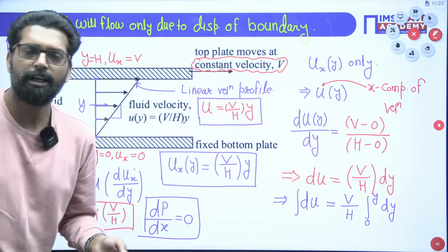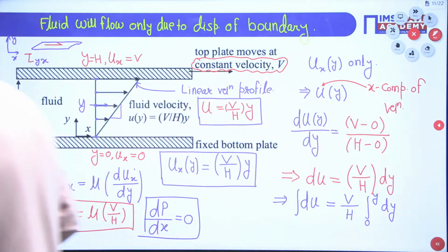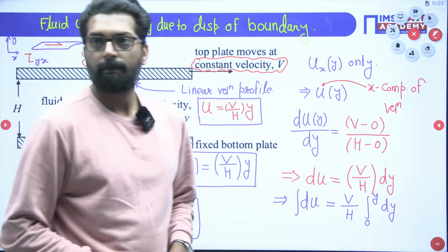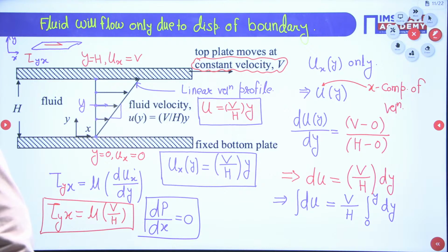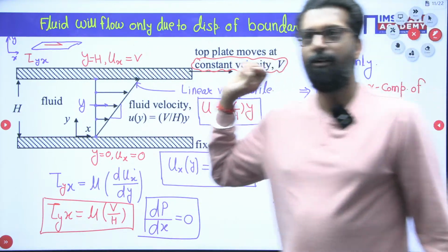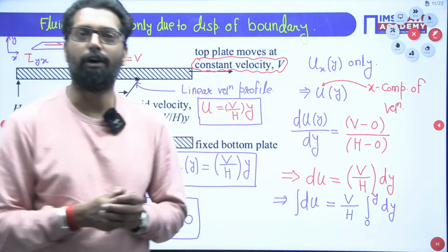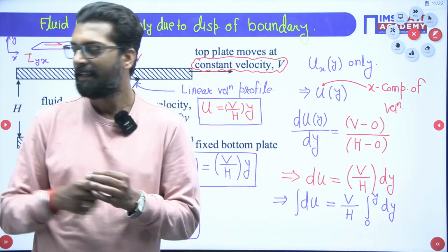It may be 0. In which case is it 0, beta? Please tell me. In which case is it 0? Everyone, anyone comment? In which case is the shear stress variation 0? Please tell me, beta. Anyone, if you have knowledge, please tell me. In which case is the shear stress 0? When the flow is uniform. When the flow is uniform, that means there is no velocity gradient.